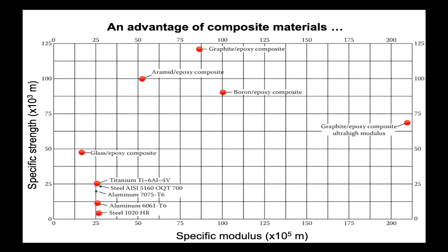Young's modulus or stiffness modulus with respect to mass is what we call the specific modulus. Strength divided by mass corresponds to the specific strength. And up on the screen now, and I don't expect you to read it from the classroom, but let me promise you, titanium, steel, aluminium in that zone, glass epoxy composites up there, and look, they're right near the zero.